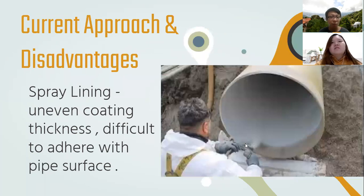There are some approaches to solve this problem, for example spray lining. However, spray lining has two disadvantages. The first is uneven coating thickness, and the second is that the material is difficult to adhere to the pipe surface. So in the long run, the materials used in spray lining will become flaky and then fall off from the surface, and the corrosion will start.